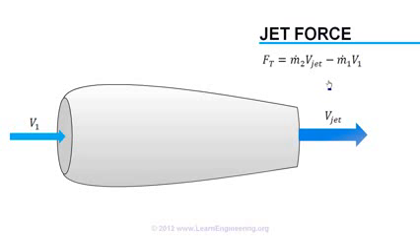So if the jet velocity is high, it means high jet force. This is why the exit portion of a jet engine has a decreasing area, if the flow is subsonic. Or, the exit portion acts like a nozzle, which increases the jet velocity.